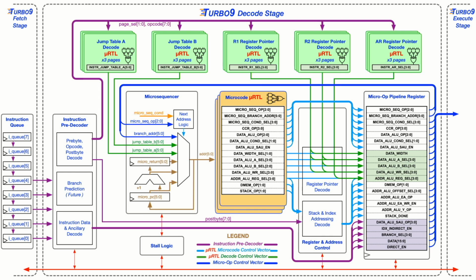So what that effectively is doing is mapping, for example, in an add A, add B, add D instruction, it's going to tell me which register to use for that particular instruction. So I'm using the exact same microcode for multiple instructions, right? I'm separating out that control from completely sequential microcode. This can just be decoded directly off the opcode and dumped into these tables.